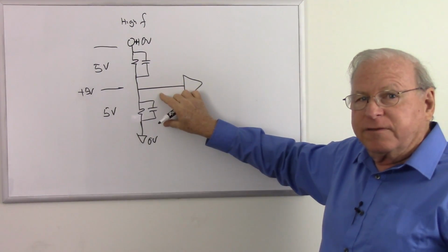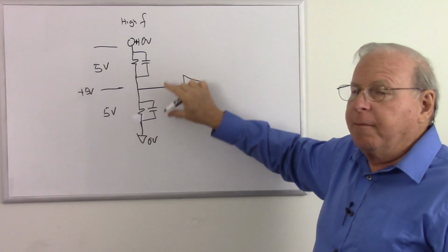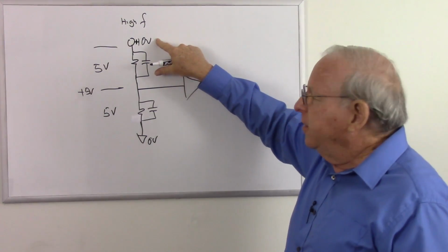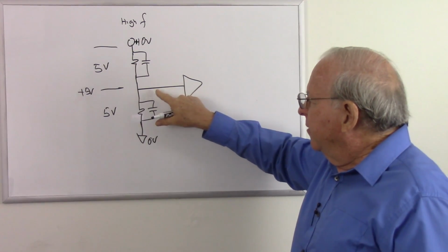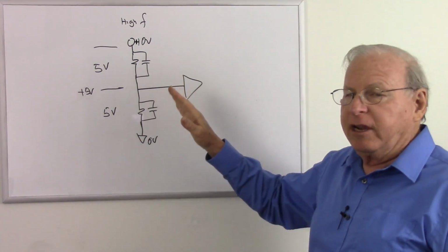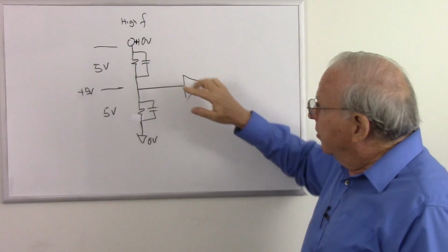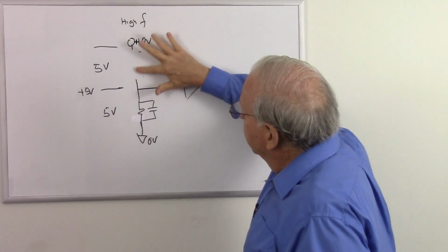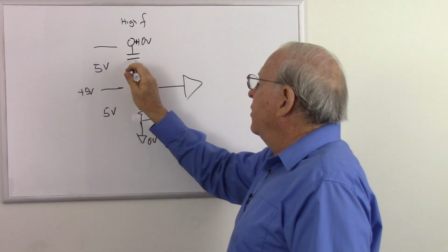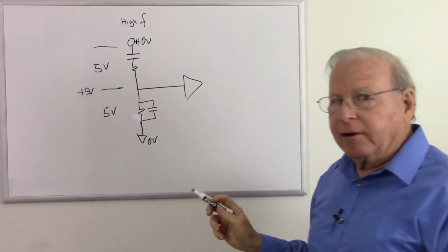What's the rule about voltage dividers? If the impedance is the same, the voltage is the same. Therefore, we start off with 10, we lose 5, and there's 5 volts there, no matter what the frequency is. So they have to be different configurations. So the next question is, why do we have it like this? We have a series configuration followed by a parallel configuration.